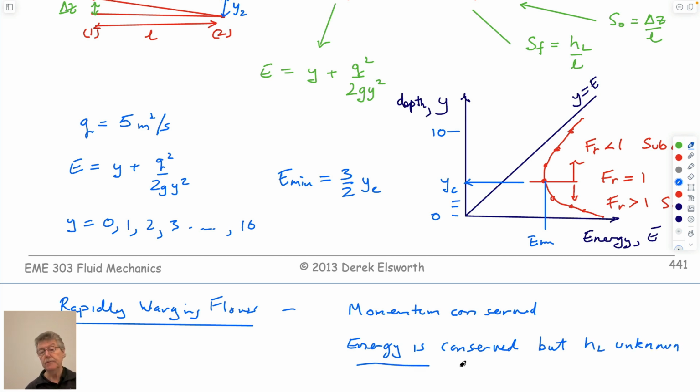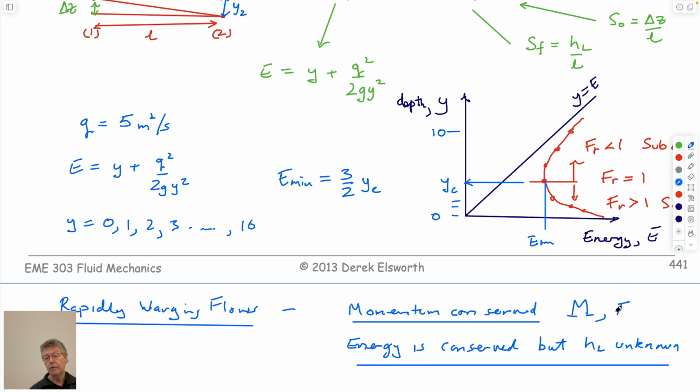So that's essentially what we did. We can calculate the momentum balance in the system in terms of this uppercase M value that we just described. If we know the upstream velocity and the depth of flow upstream, and therefore also the Froude number, then we can calculate the head loss as we go downstream. So that's it.